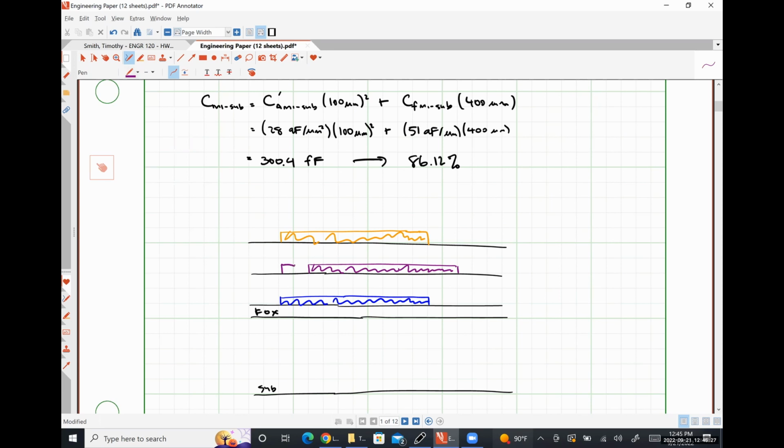So on the metal 2 layer right here, I'm going to give myself a small amount of metal so that I can literally connect my top plate, this metal 3 plate, down to the metal 1 plate, so that I have some capacitance between here and here, C metal 1 to metal 2, electrically in parallel to C metal 2, metal 3.